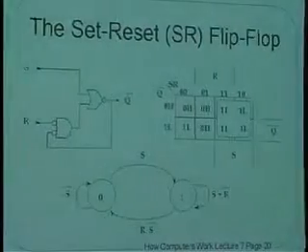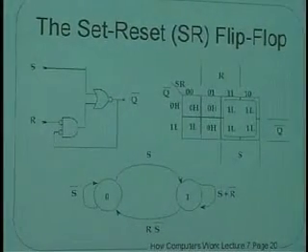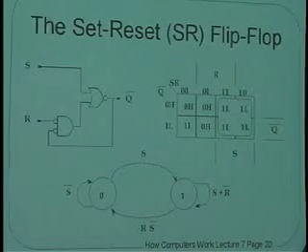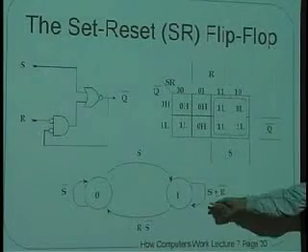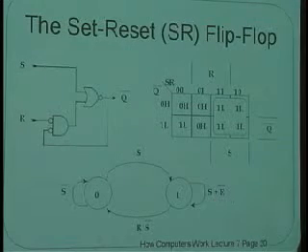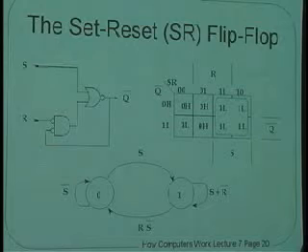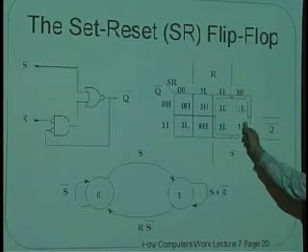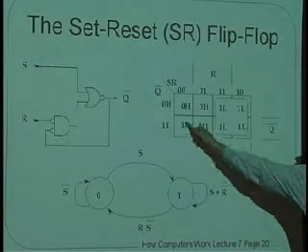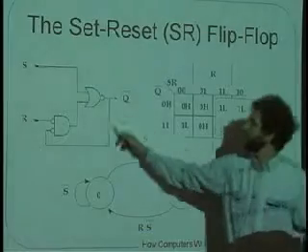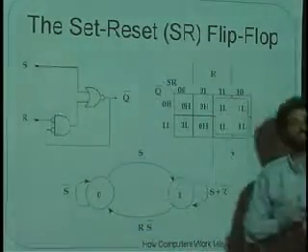Okay, there are other fundamental mode circuits, and I'm going to very briefly go through these just so that you'll see them. One's called a set-reset flip-flop, which looks like this, and the state diagram looks like that. I'm not going to go through it in detail, except to show you the K-map for it, which looks like this, except I didn't show you that the other term is this guy here. Okay, it's hazard-free. It has one bit of feedback like this, and if only one input changes at a time, it's guaranteed to work.